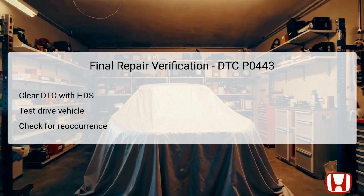After clearing the DTC, a test drive should be undertaken to observe how the vehicle behaves under various conditions, ensuring that the Evap Canister Purge valve is operating correctly without any abnormal signals. Finally, after the test drive, recheck for the reoccurrence of the DTC. If the P0443 code doesn't return, this validates the effectiveness of the repairs made, ensuring the vehicle's emission system is functioning correctly.